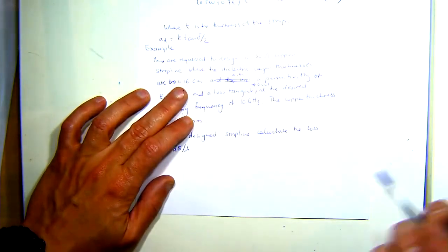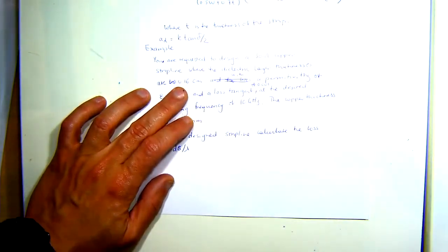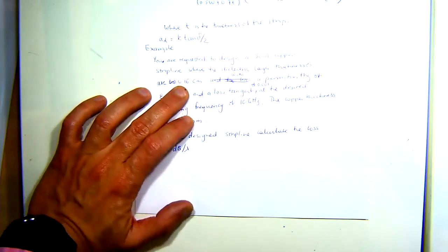It's relatively thick, but there are only certain thicknesses of dielectric material that you can buy. This is a bad data sheet, but you can't arbitrarily say, I want 1.7432 thickness of dielectric material. There are only certain thicknesses that people manufacture.